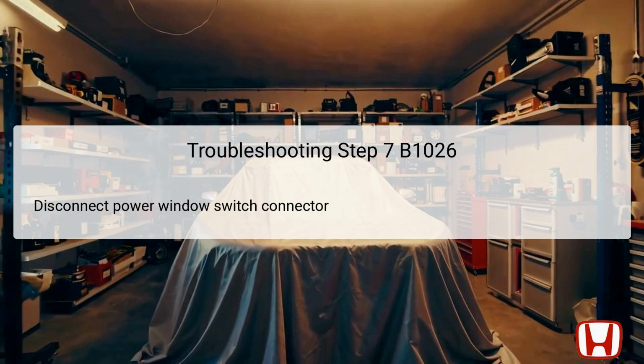Once the connector is disconnected, the technician should again check the on-off status of the door lock switch using the HDS. This step narrows down potential faults and helps in determining if the issue lies within the switch itself or if there is a communication problem with the MICU.